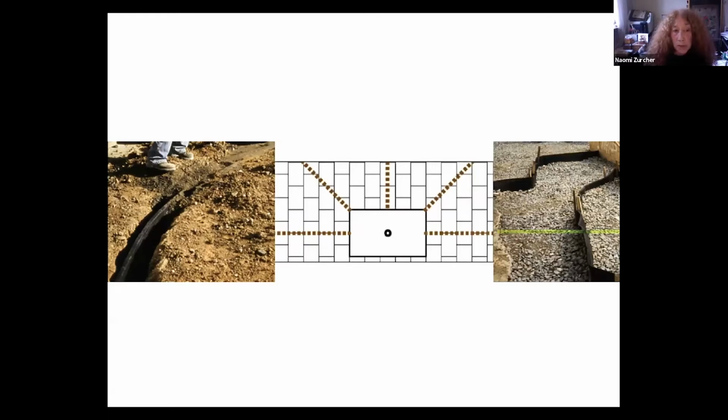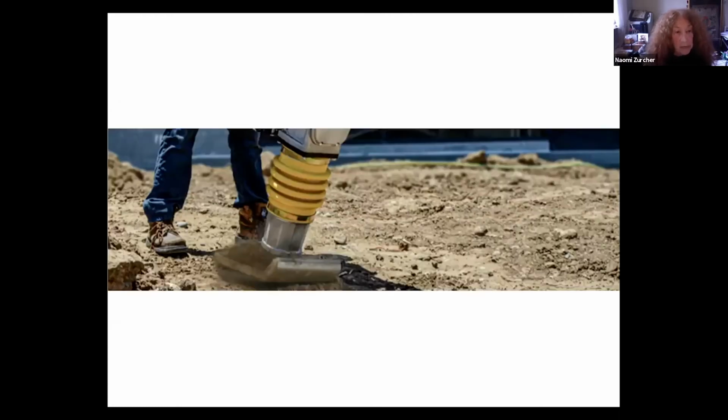The walls of the resulting path should be compacted and lined with strips of drainage board and then filled with uncompacted soil, having the same pH and soil texture classification as the soil within the planting bed. When paving is installed, compaction of the substrate is required, instigating the problems.